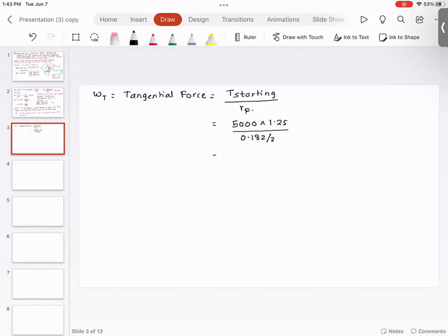So this gives me the value of WT. Next part is sigma, which is equal to sigma naught divided by velocity factor. Sigma naught is 140 and the velocity factor is 0.26. So this is what we got.